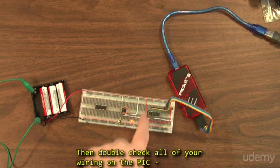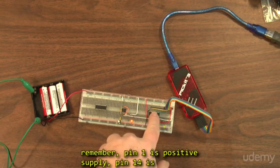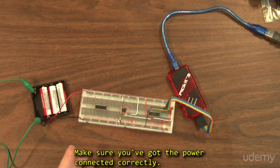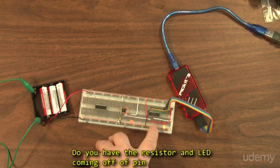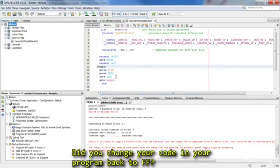Then double check all of your wiring on the PIC. Now remember, pin 1 is the positive supply, pin 14 is negative. It's like the chip is built upside down. Make sure you've got the power connected correctly. Secondly, is the clock pulse going from the 555 to pin 2? That's the clock input pin. Do you have the resistor and LED coming off of pin 7? That's the pin we programmed for the output. Did you change your code in your program back to FF?